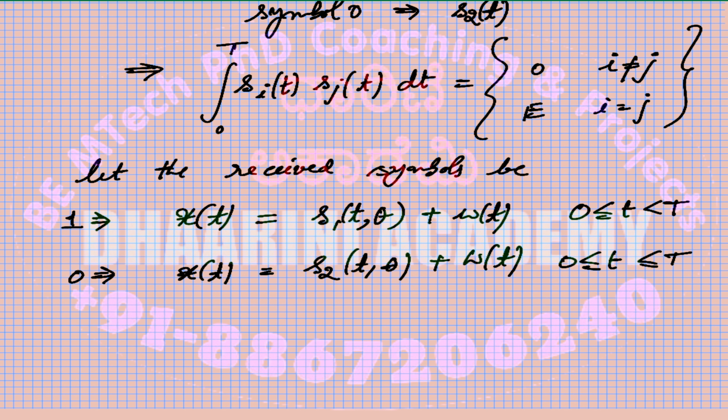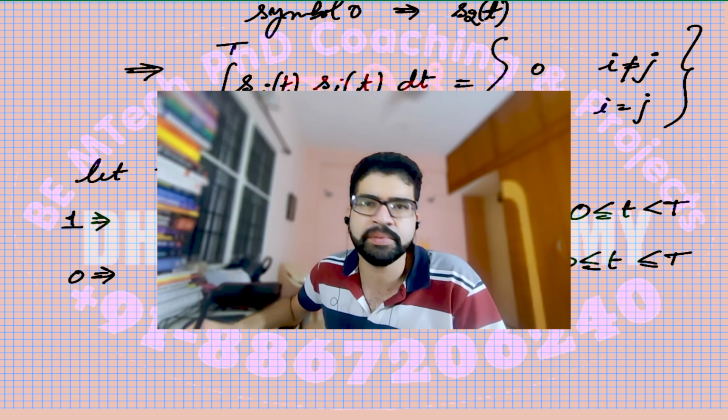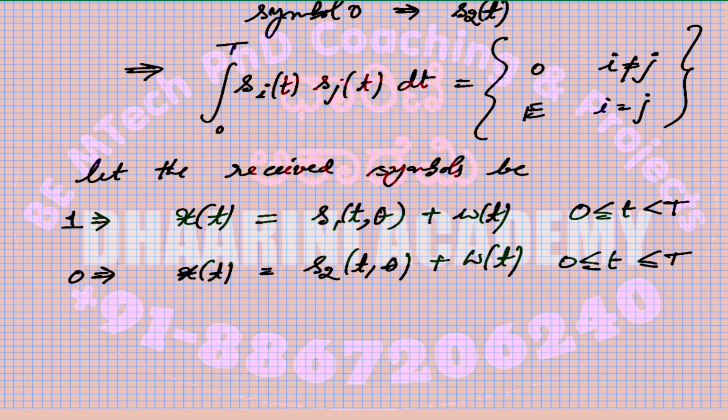It also depends upon the signal strength and what type of noise sources are present in the channel. Is it outdoor, is it indoor, etc.? How many types of scattering happen? How many copies of waves will be generated by the modulator, and what is called a multipath? Those concepts will be used ultimately when the signal reaches the receiver. How many copies of the original signal come to the receiver at a given point of time depends even on that.